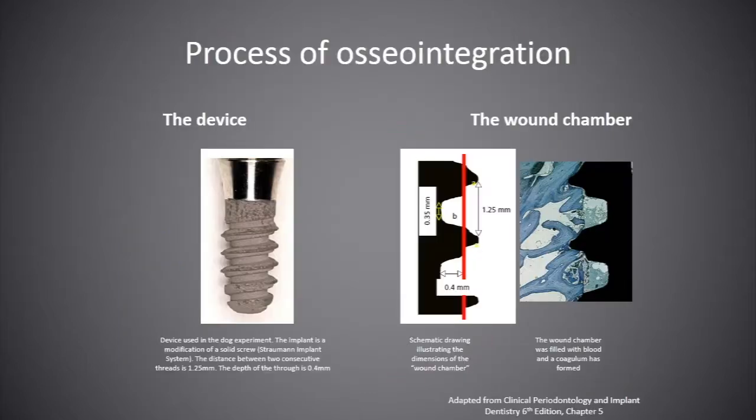The figure on your left is a custom-made implant made of CP titanium in the shape of a solid screw and configured with rough surface topography. In the implant device, the distance between two consecutive profiles of the pitch was 1.5 mm. A 0.4 mm deep U-shaped circumferential trough had been prepared within the thread region during manufacturing. The tip of the pitch was left untouched.